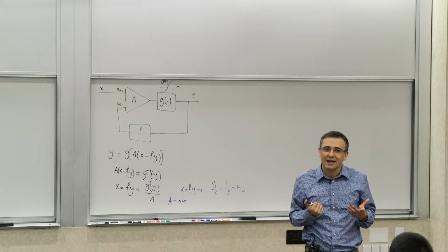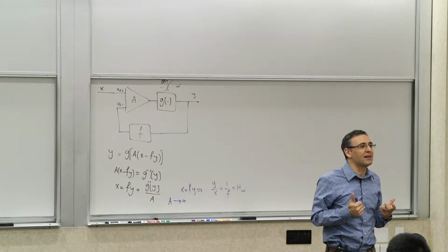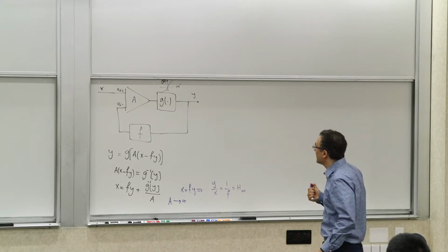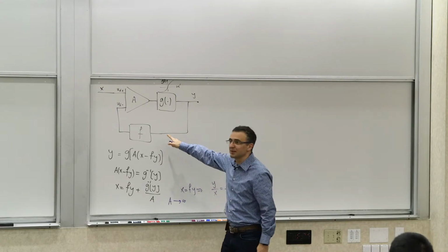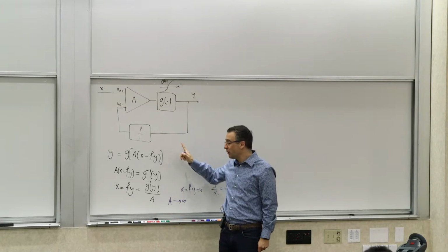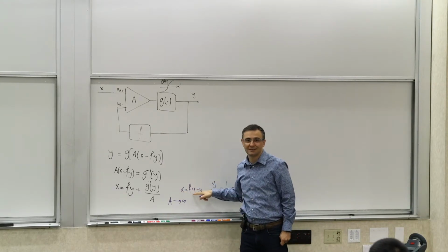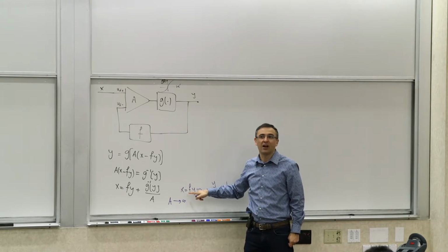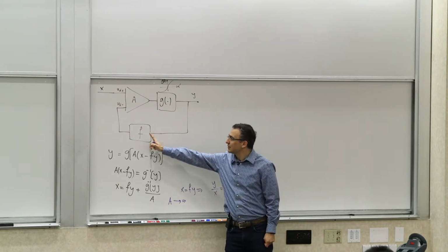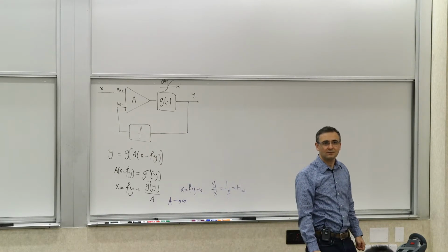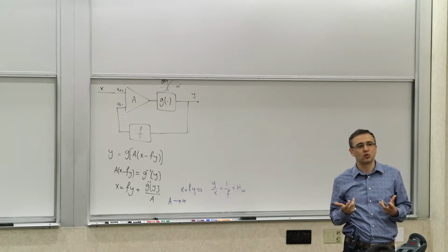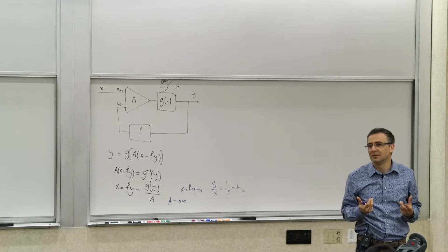But what it tells you is that if you have even a highly nonlinear amplifier that has a lot of gain, then essentially its nonlinearity will disappear in the feedback loop. And you will get a gain that's both linear, or linearized, and determined purely by the amount of feedback you apply. So feedback, one of the major things it does, it actually reduces the distortion, the nonlinearity in the system, right?